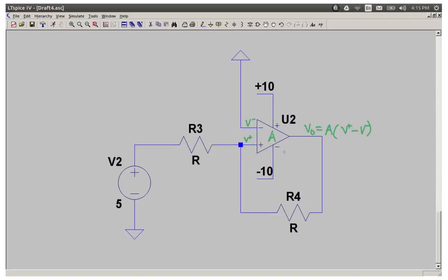But in this case, the one thing you can see very easily is that if you have a large output, let's say it's stuck at plus 10 volts, then the 10 volts can feed itself. This is a positive sign, this is at ground, so the 10 volts, as a part of it, feeds itself and can keep feeding itself. So this is called regenerative positive feedback. It generates itself again and again, and this makes it get stuck at that 10 volts that it started with.